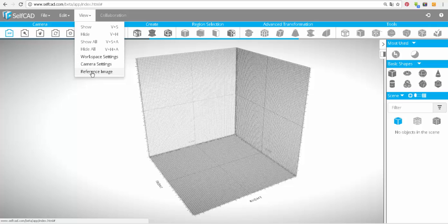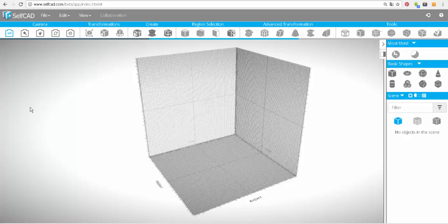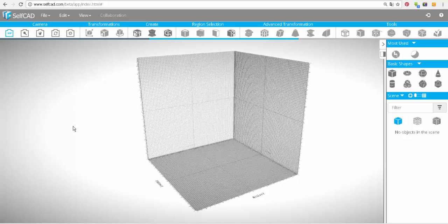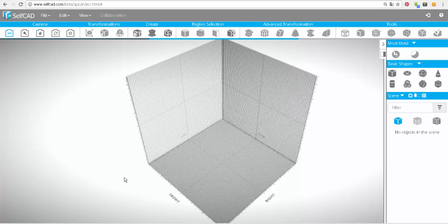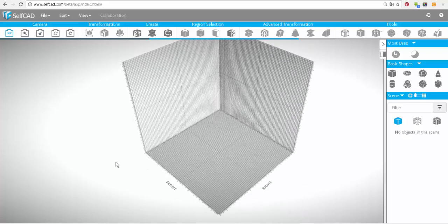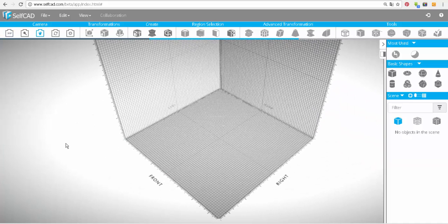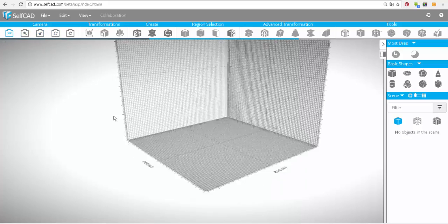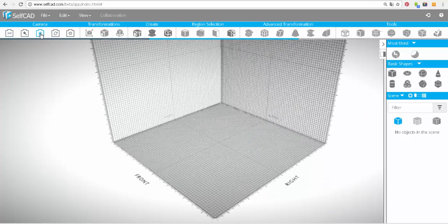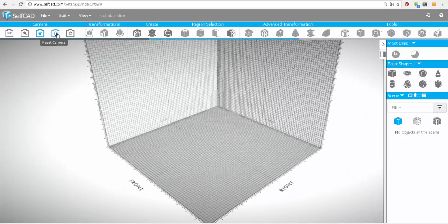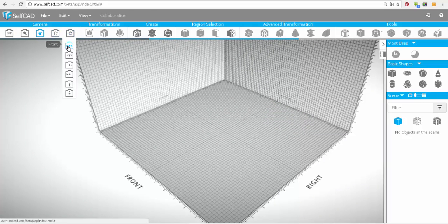Using your mouse, you can do all the camera transformations without switching between camera modes. Hold the mouse left button and drag the mouse to rotate the camera. Hold the mouse wheel to pan the camera and scroll the wheel to zoom in and out. In the camera section, you can also switch to different camera modes. Right now it's in rotation, and I recommend leaving it that way and using scroll for other modes. There's also an option to reset the camera and focus the camera.